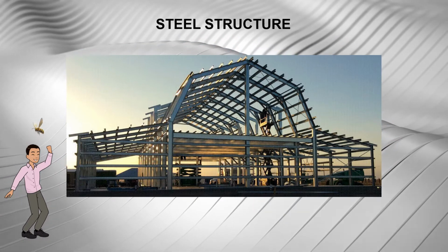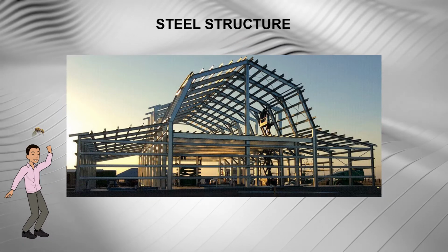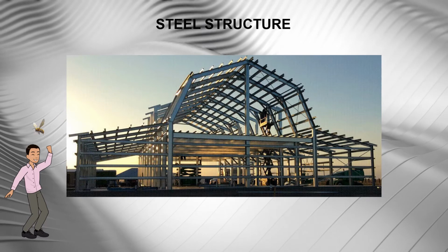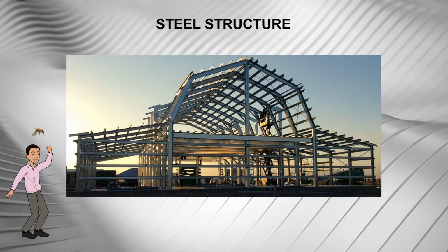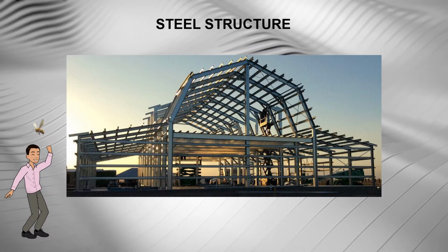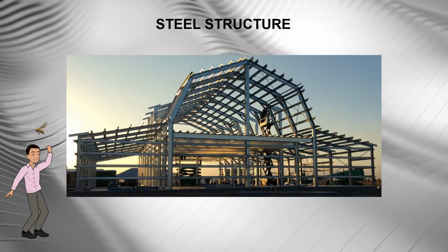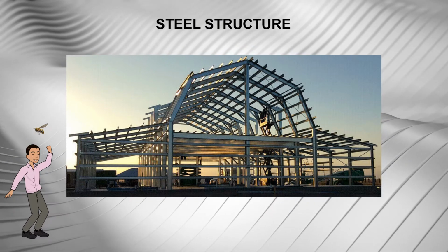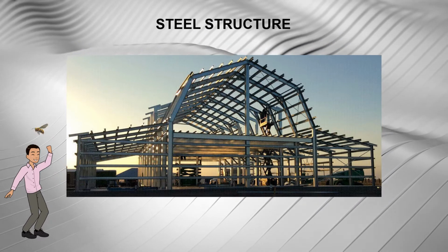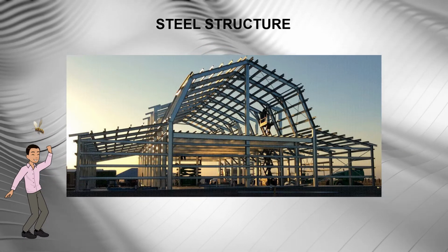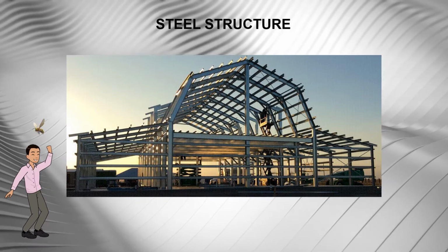The ability to provide spans up to 60 meters, but more commonly around 30 meters, using steel has proved very popular for commercial and leisure buildings. The lightness and flexibility of this kind of steel structure reduces the sizes and the cost of foundations and makes them less sensitive to the geotechnical characteristics of the soil.